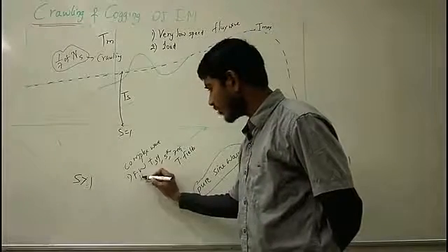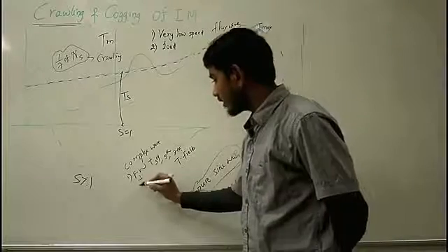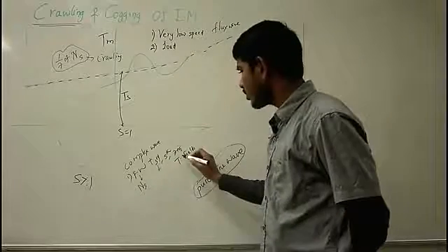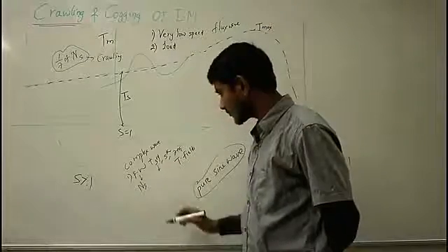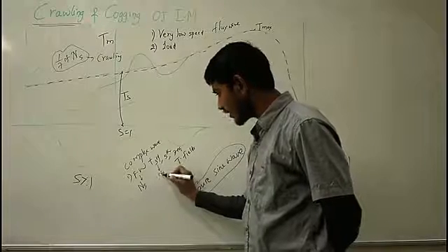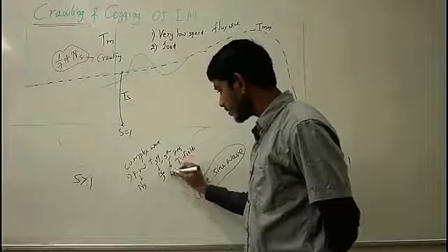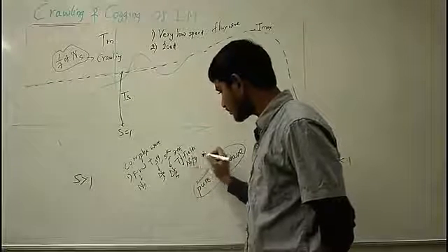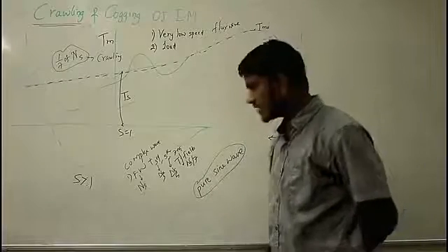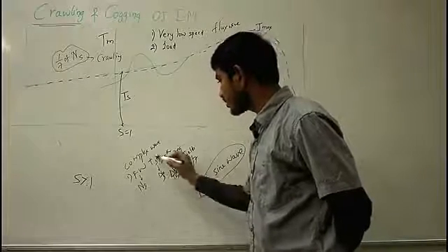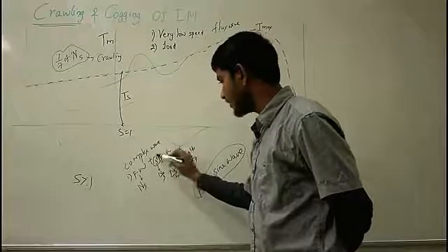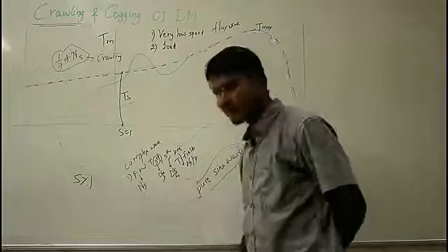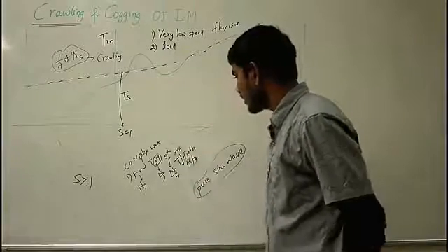The fundamental wave revolves synchronously at synchronous speed Ns, whereas the torque field produced by the third harmonic revolves at the speed of Ns/3. Similarly for the fifth harmonic, Ns/5, and for the seventh harmonic, Ns/7. In a balanced three-phase system, the third harmonic is absent. That means the torque developed by the third harmonic cannot be seen in a balanced three-phase system. Now we are left with the fifth harmonic and the seventh harmonic.